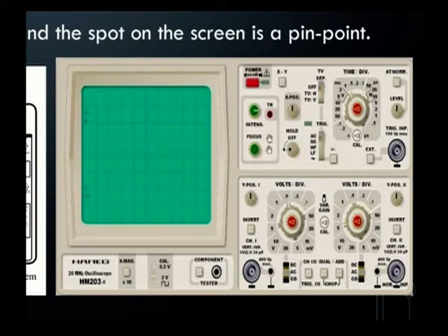This is, as I said, a power. This can be used for the voltage per division. We can control along the y axis; the amplitude, everything can be varied with the help of these two knobs. And this is the time division axis, so that the horizontal movement of a signal along time can be achieved with the help of the time division knob.